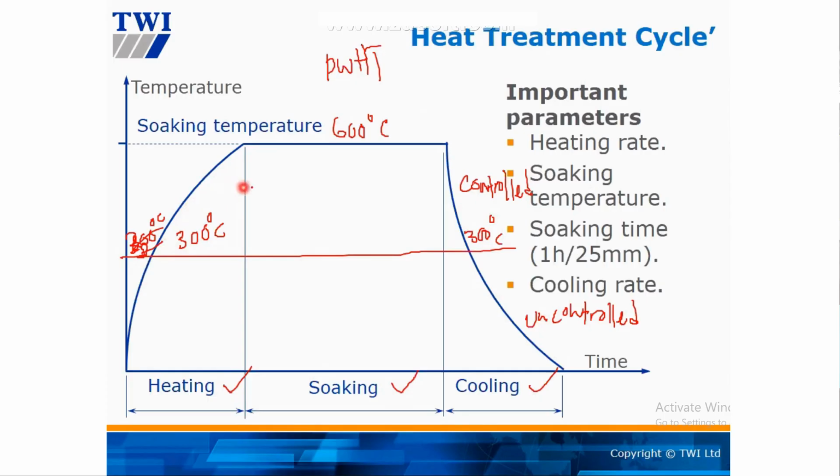Must be not more than, according to TWI spec, maximum 220 degrees C per hour. Okay? All right.